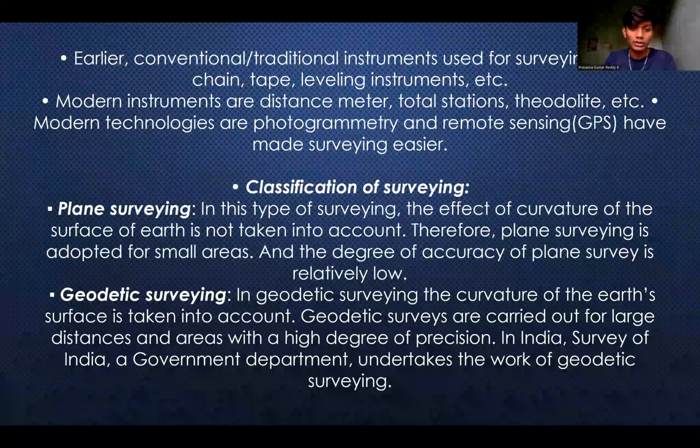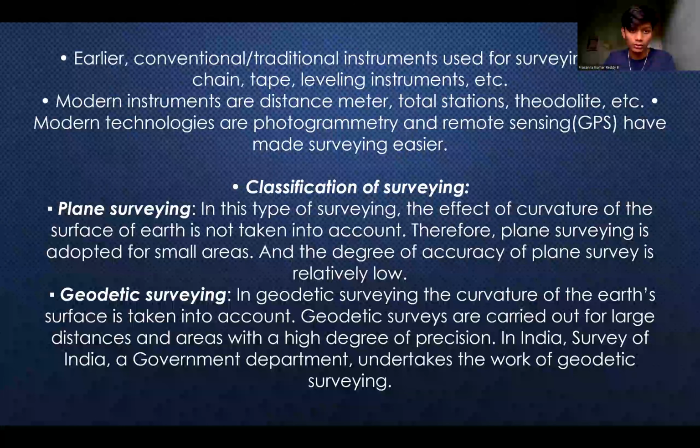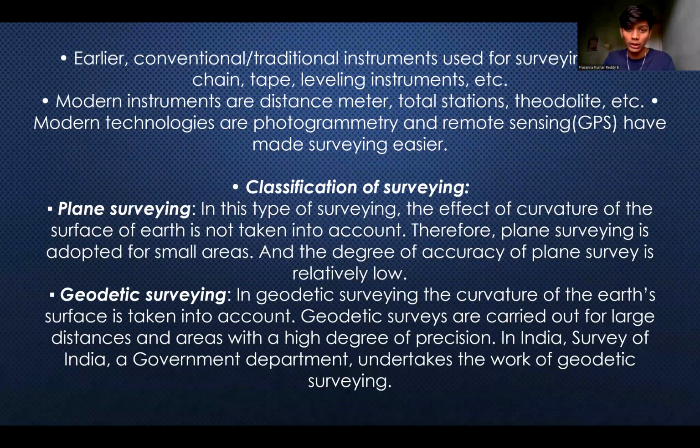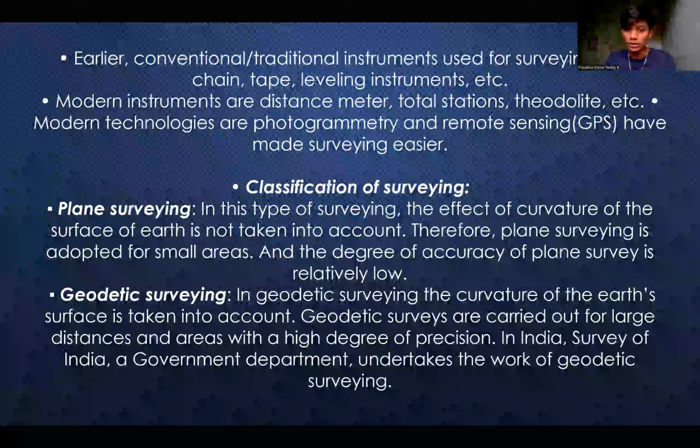And geodetic surveying. In geodetic surveying, the curvature of the earth surface is taken into account. In plane surveying, it is not taken into account. Geodetic surveys are carried out over large distances and areas with a high degree of precision. In India, the Survey of India and government departments undertake the work of geodetic surveying.